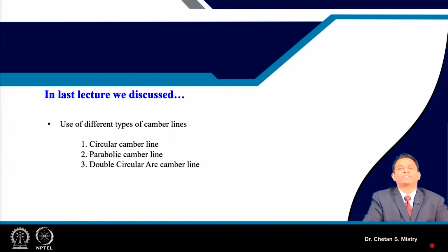There we have some limitations in terms of location selection and the formation of the shape. The double circular arc gives us more flexibility in terms of the location at which we are looking for turning of the blade. So we have our beta at the junction, and our x or percentage chord at the junction point from where we can modify the shape of our camber line.